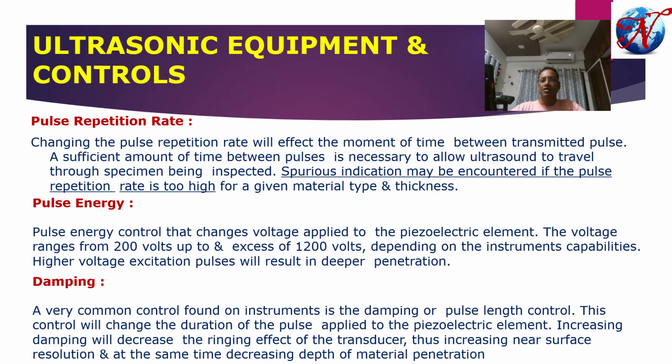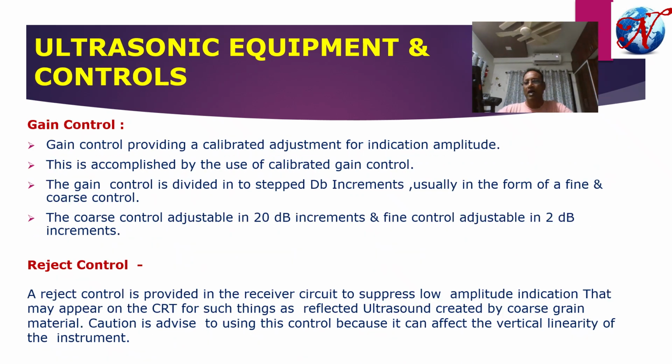Each and every ultrasonic equipment has a damping control to control electrical noise or excessive vibratory noise. Any kind of electrical interference or electrical noise is internally damped by the machine hardware and software itself. Each and every ultrasonic equipment also has a gain control unit. Gain control is also indicated as a dB control.